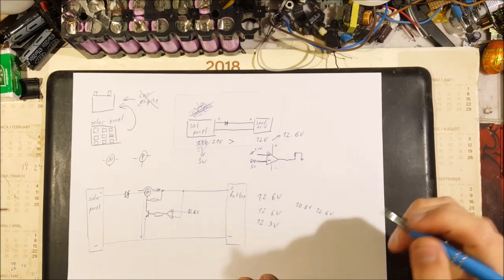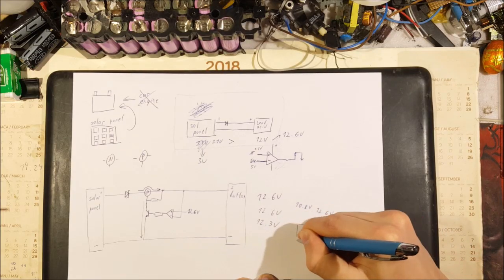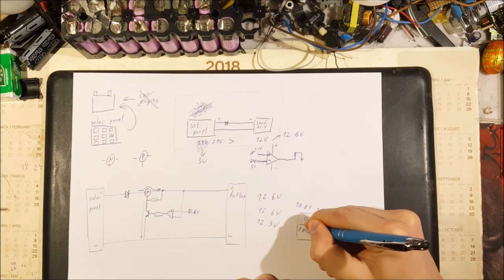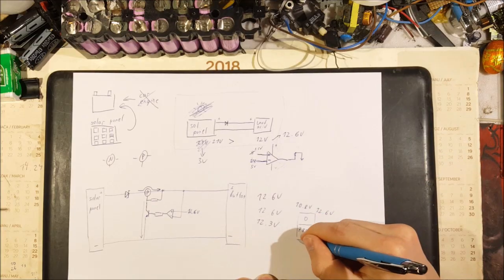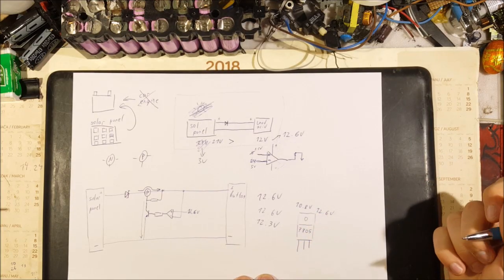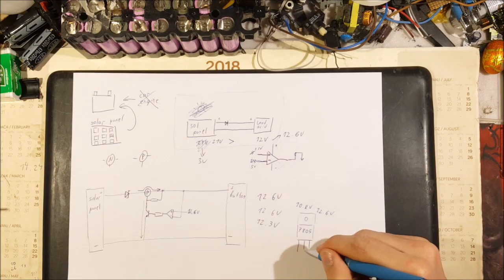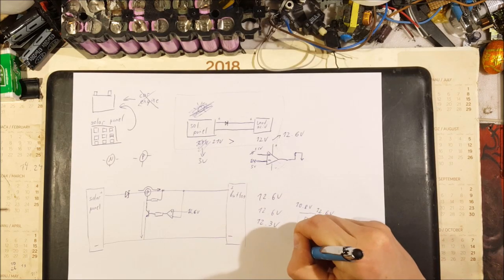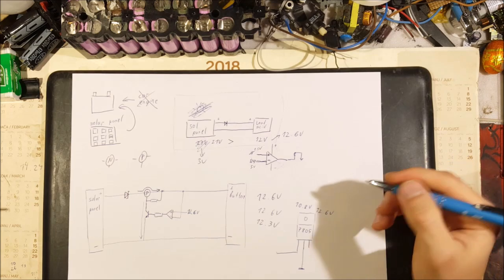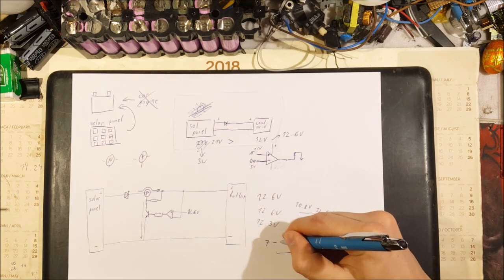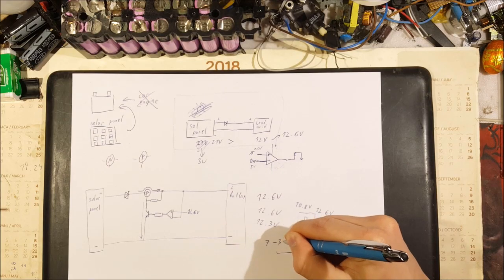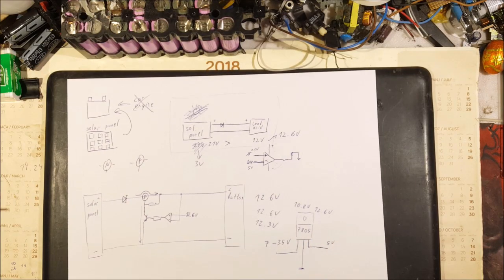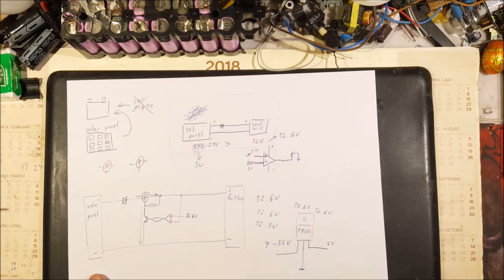So why not use a little linear voltage regulator, which can be, say, 7805, which has 3 wires. It looks like a transistor, but basically the way you use it is you connect the middle wire to ground. First wire goes to basically any voltage between 7 to, I think, maximum is 35 volts, and the output will be always 5 volts. Now let's use that as a reference.